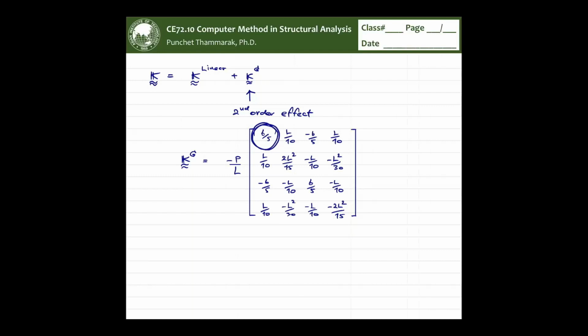6/5 multiplied by P over L. P is a force, L is the length scale. So the same thing, okay, are put together. You cannot have any inconsistencies in the unit because you add these two up. Okay, right. So knowing all of this, we can move next into the calculation, maybe in Microsoft Excel, in order to figure out the buckling load.